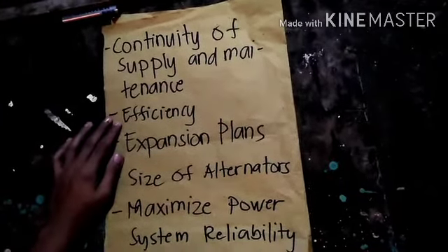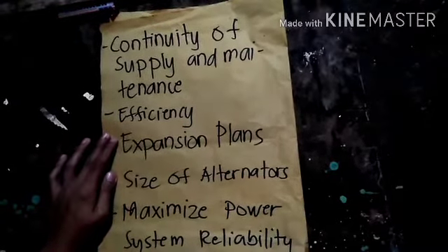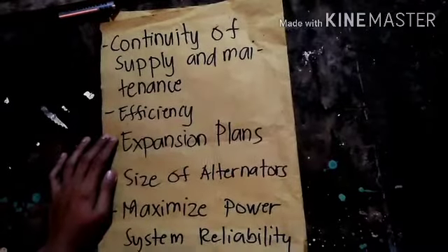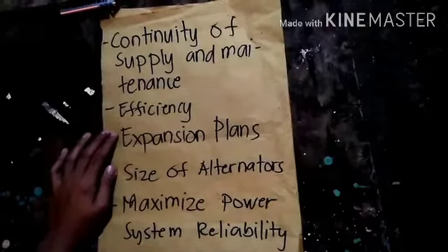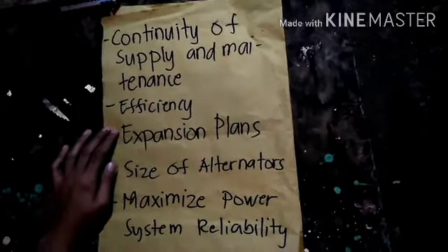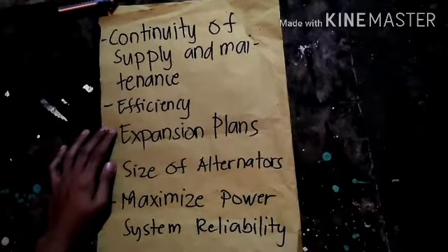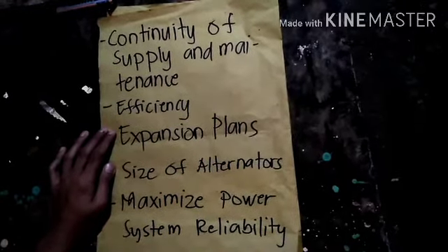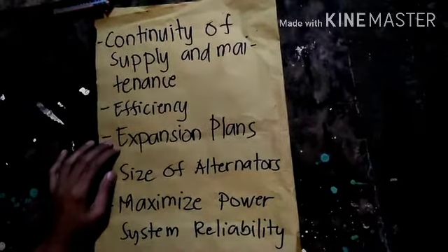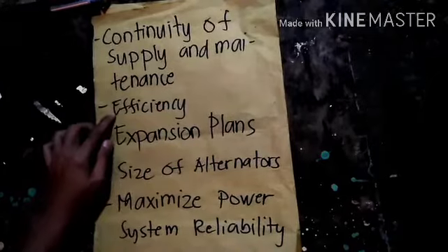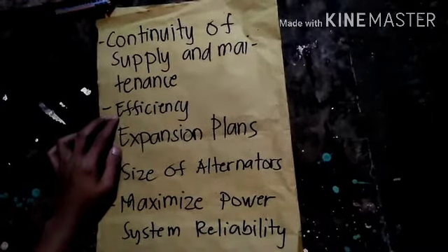Next is efficiency. Efficiency versus load curve. Generator efficiency is maximum when the load is 100%, so the generator unit must run on full load. A single large unit would be uneconomical for lower loads. But with smaller individual units, we can add up or switch off the generator units as per the load requirements in order to meet the maximum efficiency.